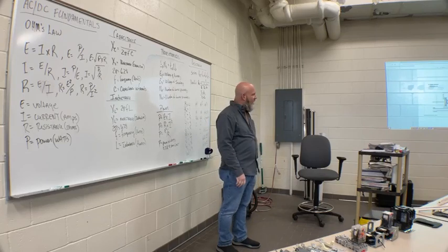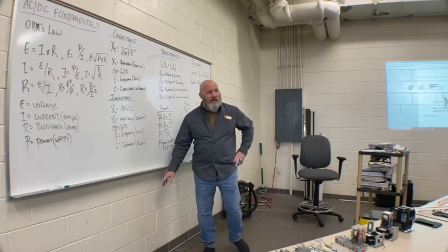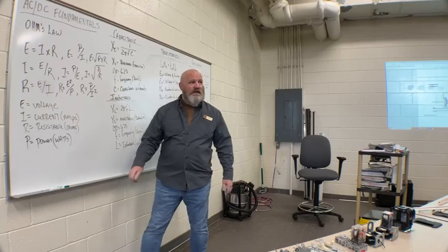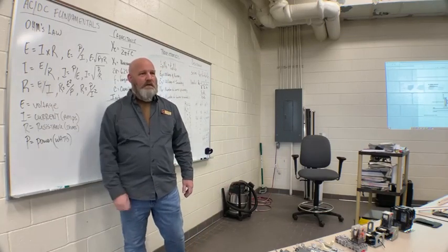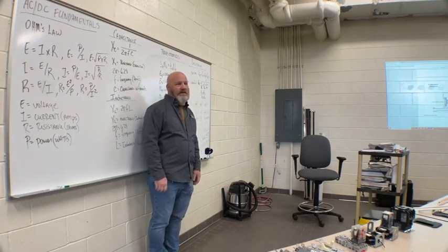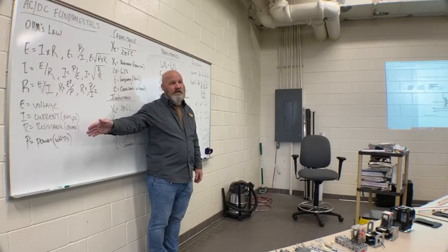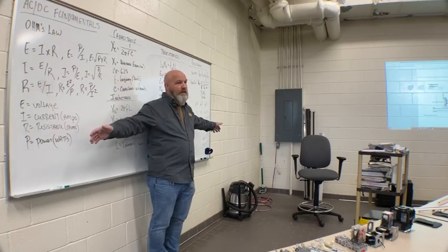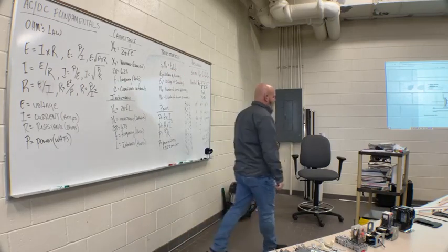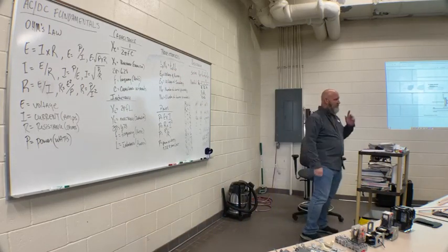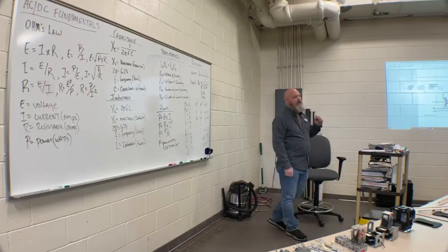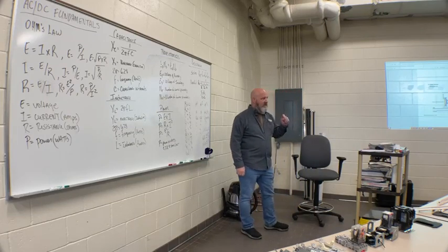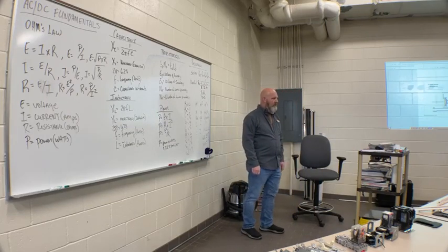How'd you get 12 feet out of that? Any place along the line of the wall cannot be more than 6 feet from a receptacle. That means if I'm standing dead in the center, I have to have a receptacle 6 feet that way, or at least one 6 feet that way, so that makes them 12 feet apart. You'd be surprised how many electricians miss that on the test. They will pick receptacles need to be 6 feet apart because they see 6 feet in the code book.